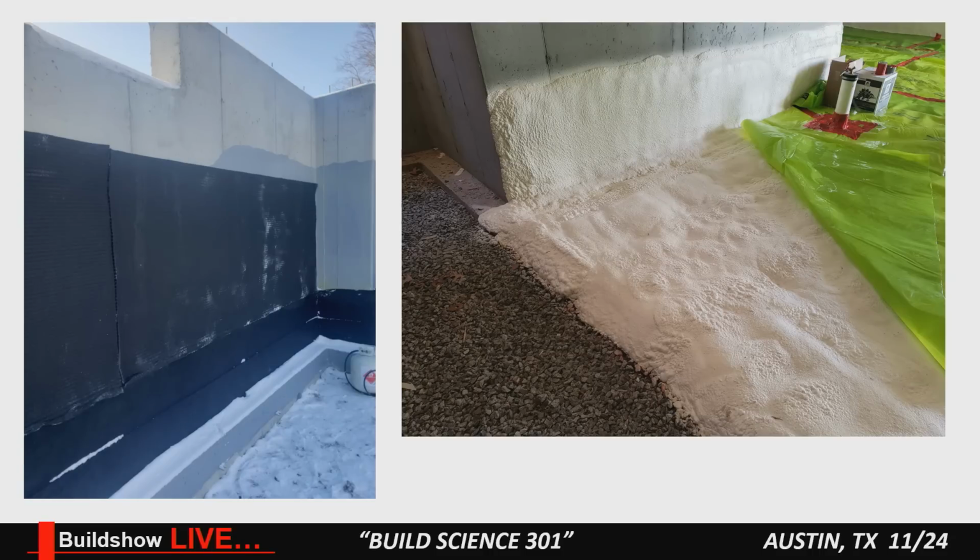Our good friends at Polyguard, right? Total flow, lower Arroyo section drain. Yeah, they have their waterproofing system, their blue barrier, the spray-on adhesive, the drainage mat with mesh, so a total system. This is just a closed cell insulation job, Stego over the top.